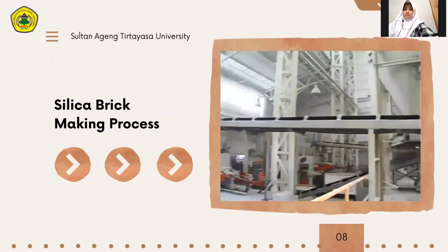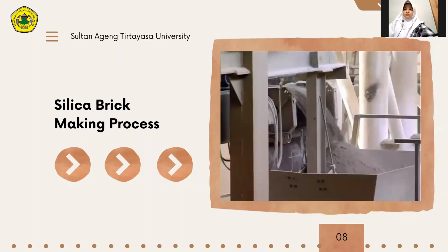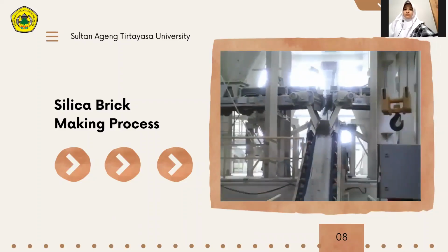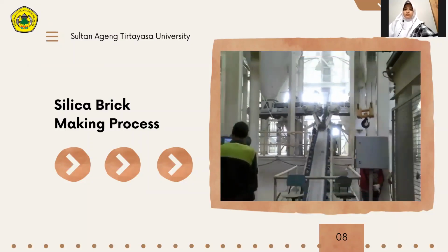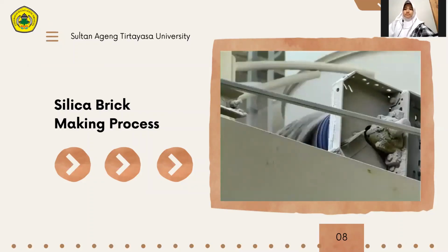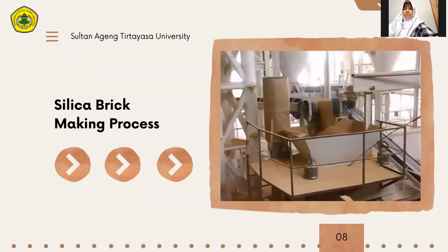After the reaction time, approximately 2 hours, the mass, approximately 16 degrees, moves to a twin-shaft mixer for additional mixing, to be additionally moistened until it obtains plasticity, which is necessary for press forming of sand lime bricks. Then the mass proceeds to hydraulic presses WKP 750, WKP